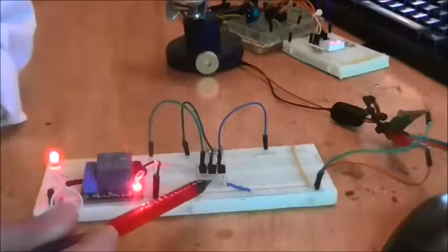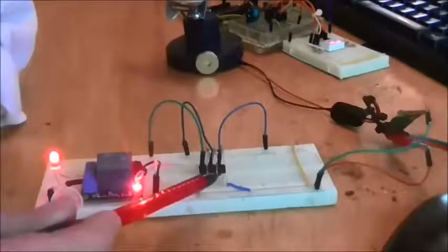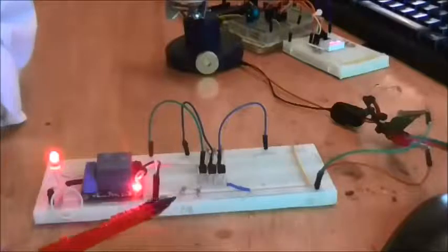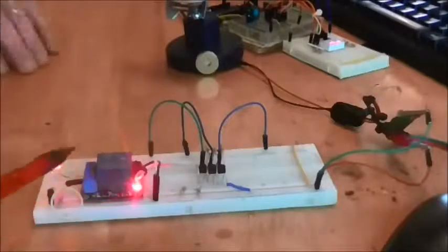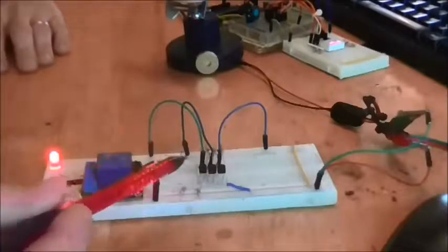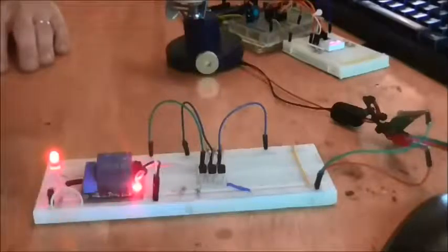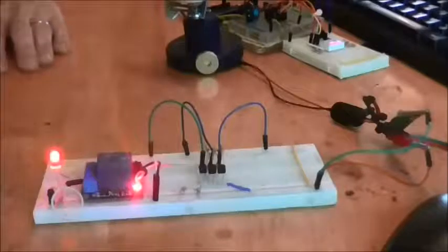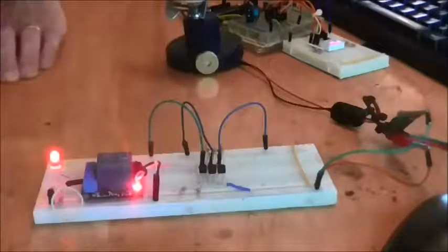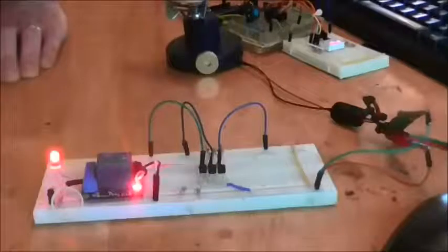And the pamphlets to go with this, I'll put the schematics for this AND gate and we'll see how we've done it. However, at the end, at the output, I've put a relay system. Now there's a reason for this, and the reason is that it's going to be difficult to fan out. And what I might do is put something with a bigger impedance on the end of the AND gate, and that will disturb the balance and things won't work as they should.